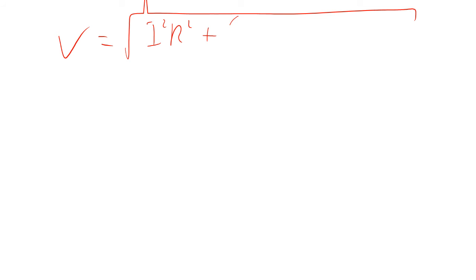that voltage equals the square root of I squared R squared plus I XL minus I XC squared.